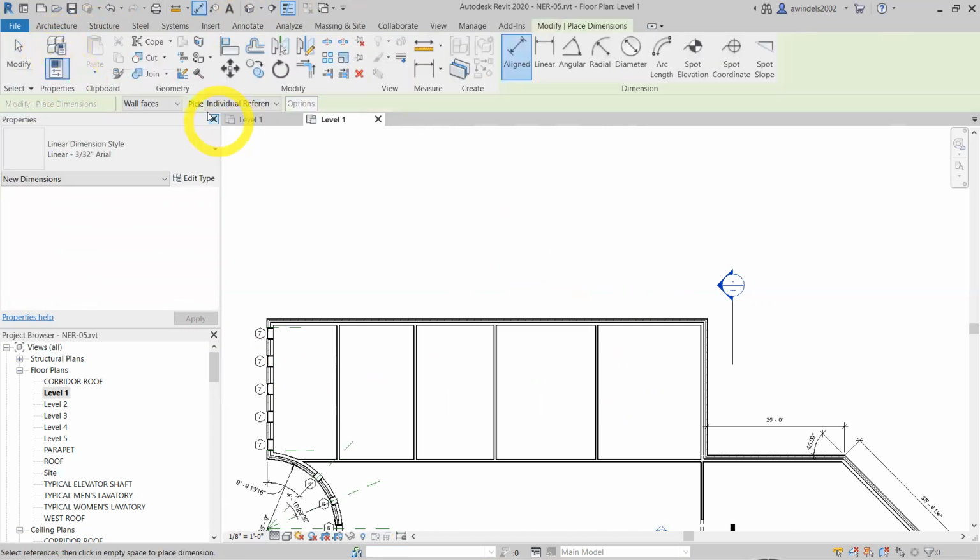And in the options bar, say center of core. So this goes to the actual full center of the core, the structural part of the wall. In this case, the interior walls, it's one and the same as the wall center line and center of core are the same. Bigger exterior walls, they can be different centers. So just think about that. Select that.